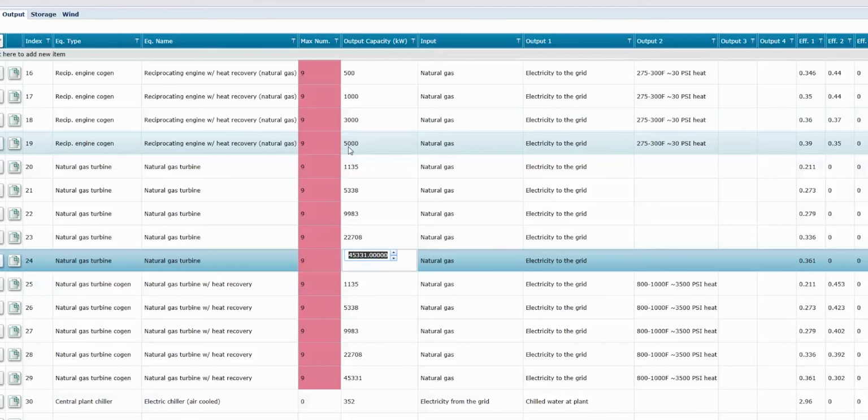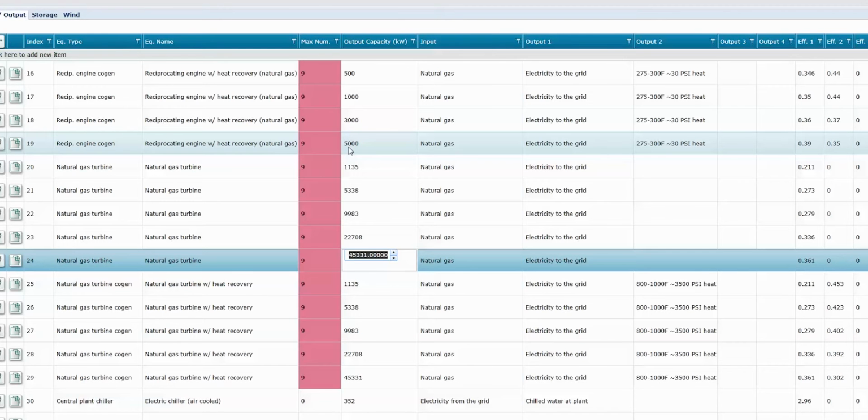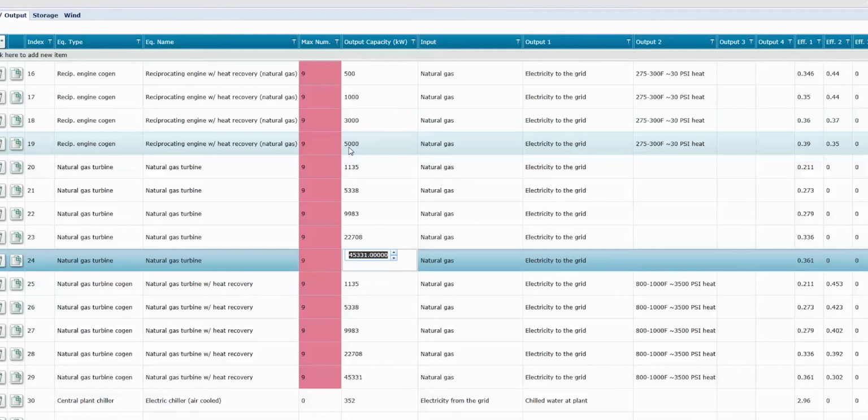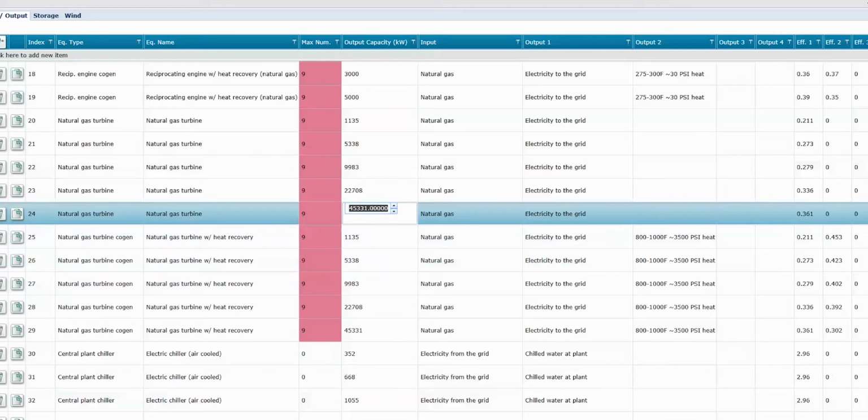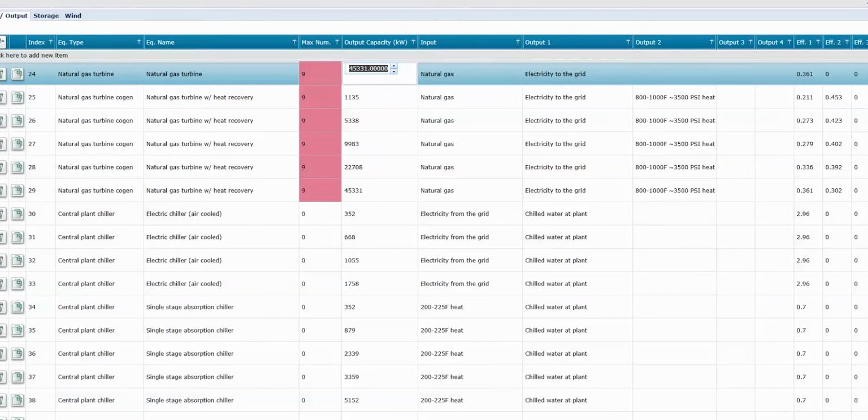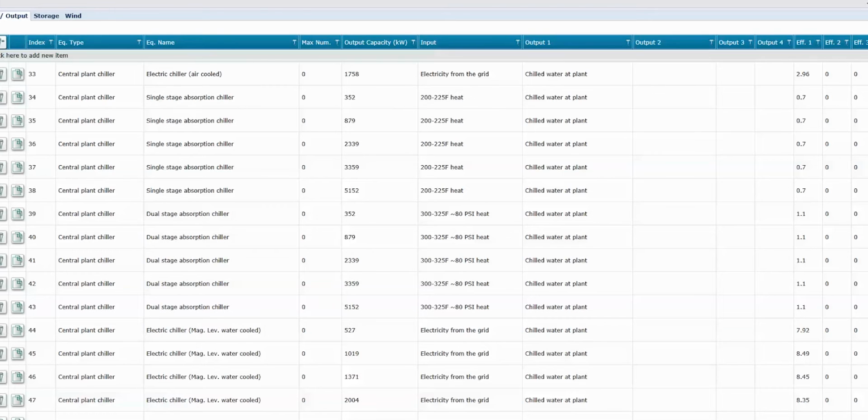It turns out that for most of our installations, if you're trying to match up with the heating demand at all, which is usually the most cost-effective way to size these things, the scale is much closer to that of reciprocating engines. I haven't found a location yet where natural gas turbines were going to be a great solution, and it's primarily based on that scale. We just don't have that dense of development for most of our installations, because land hasn't been nearly as critical to force us into very tight development. And so I'm going to allow them as well, but I wouldn't expect turbines to be part of the solution for this group.